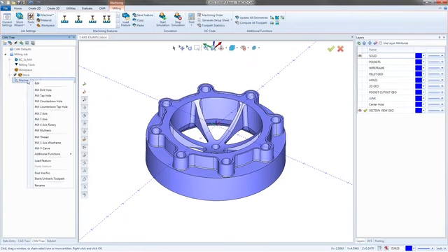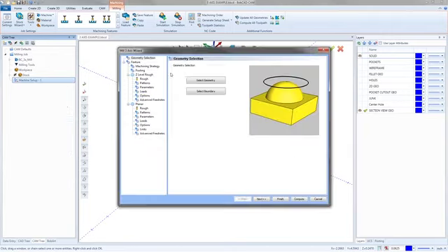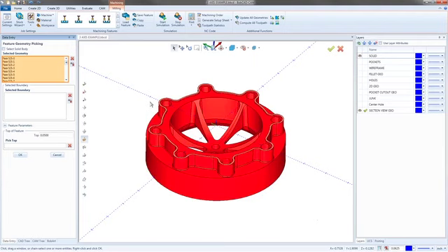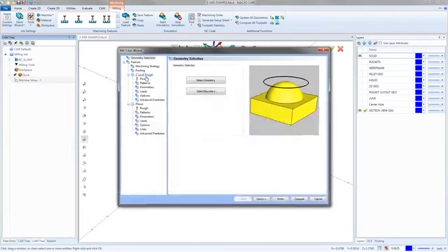And so when we go in here, if I right click and I go down to my mill 3-axis, the first toolpath I'm going to create is going to be just my roughing toolpath. I'm not going to put any finishing passes on it at all, because my finishing passes are actually going to use a different piece of geometry. So first off, select geometry.